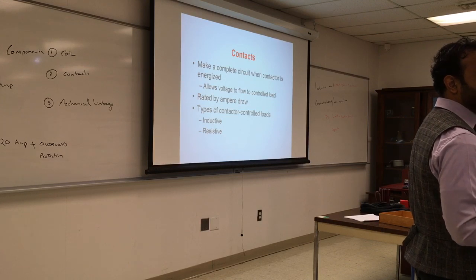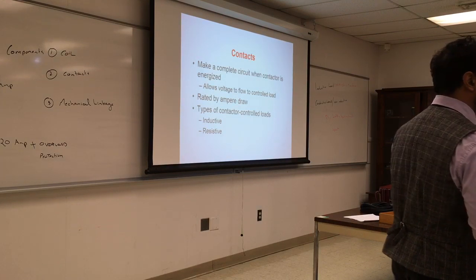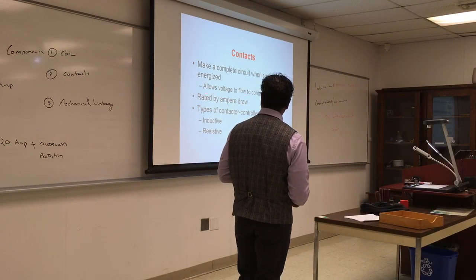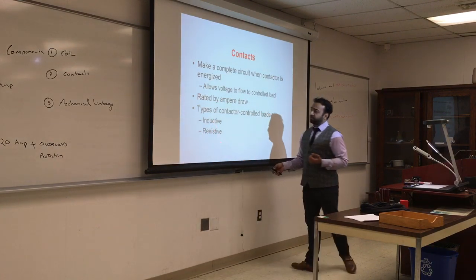What happens if you have halfway contact? It will buzz, it will not give you good connection, and can overheat and cause spark or fire. Type of contact control loads, inductive and resistive.